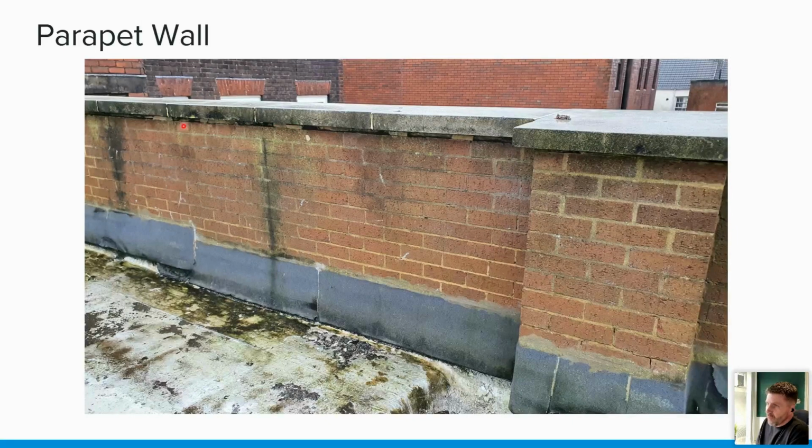Because as you can see, what happens over time is the bedding mortar will start to erode. These mortar joints are always an issue when it comes to concrete coping stones. You need to be looking at that. So if we can get rid of them and take the waterproofing up and over the top, that's my favoured detail. The other thing we need to be looking at as well.